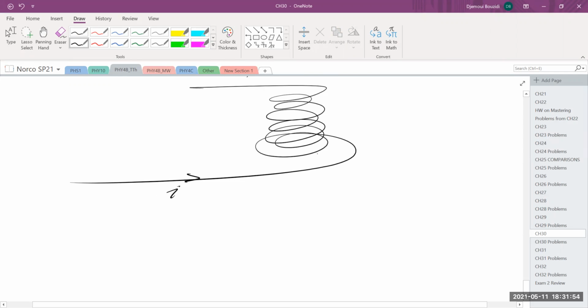When you multiply it by the area, you're going to find the magnetic flux for that wire with itself. And you're going to multiply it by N and the area in this case to find the flux, and you multiply it by N again, and you're going to find the flux that is actually opposing this whole thing. So the flux in this case is going to be L by definition, not M, times I, where L in this case is the self-inductance.